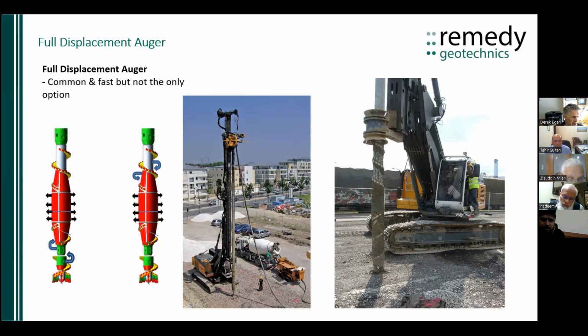So you haven't got to do any of that work. So the construction, say, of a floor slab or a foundation can go ahead as though there were no piling. So I suppose to answer the question, yes, they can be designed for lateral loads, but it becomes much more difficult and problematic.